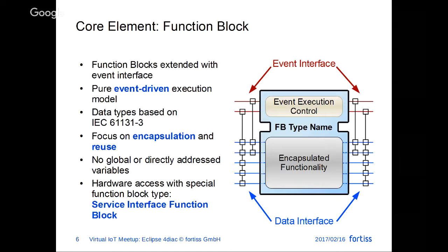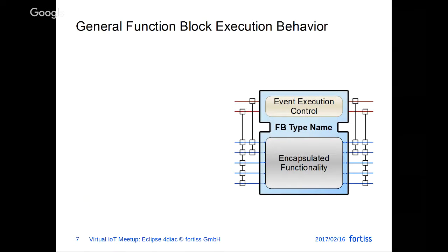So IEC 61499 function blocks are passive. They are in your application and wait for events to do certain actions. And this is a very interesting concept, especially when it's coming to distributed and networked control devices, because now you can synchronize yourself to network messages, and you can, as application programmer, define in a graphical notation when to send messages on the network. I will briefly go through how function block execution is working.